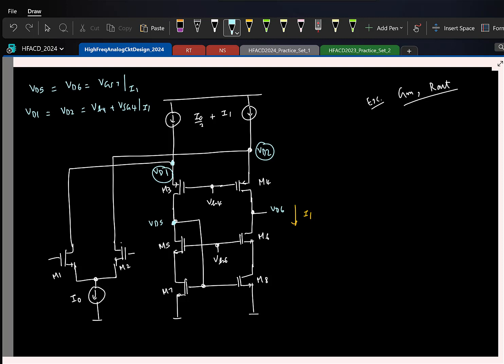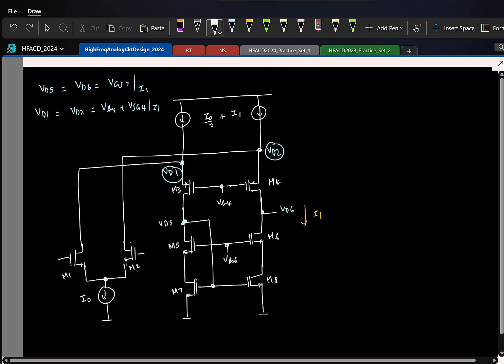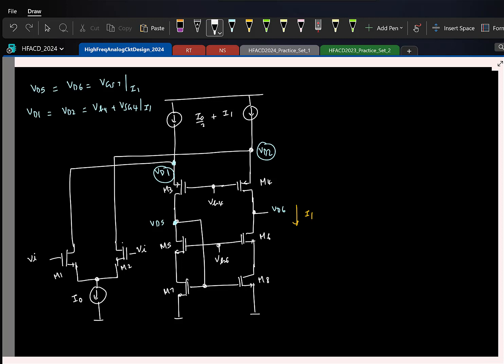So then let's find the same two things again, common mode range and slew rate. Let's do common mode range because that might be shorter to do. Let me copy paste this. We have done this before. For common mode range, I'll assume that I'm applying the same input to the two gates. Let me also replace all these with transistors. So here I have M0.